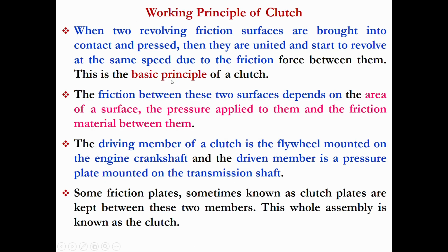Here the two revolving friction surfaces are made to contact each other and are kept under pressure in the engaged situation. Then the driving end makes the driven end rotate and transmit the power. So the power is transmitted from the driving end, that is the engine side, to the gearbox end.